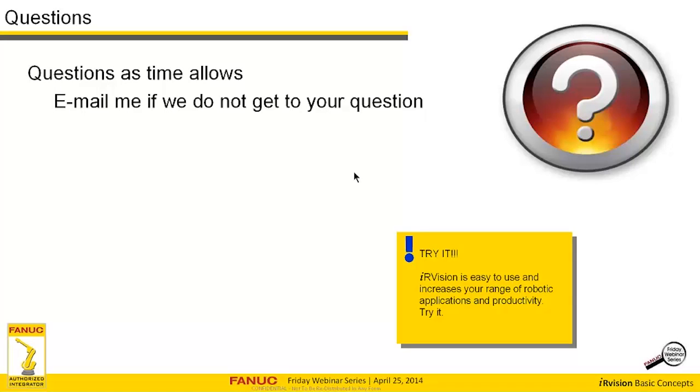One question that I often get is, when should you use auto grid frame set versus robot generated grid cal? Basically, robot generated grid cal is very good for large fields of view. Actually, with our new 3D area sensor, the field of view of each camera is quite large, and so you pretty much have to use robot generated grid cal.